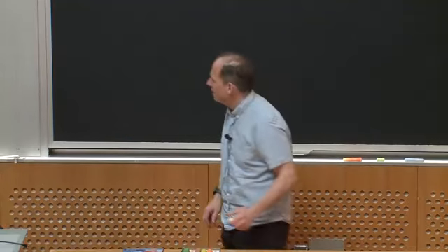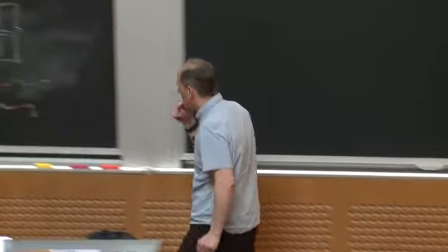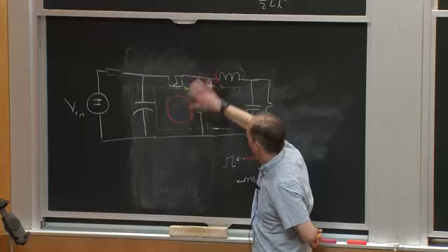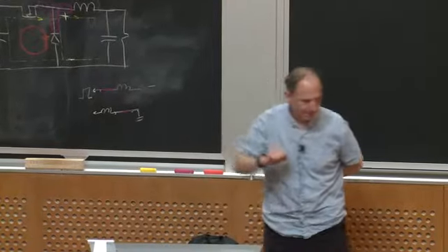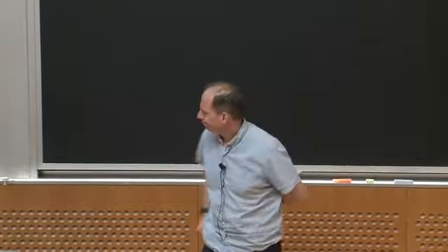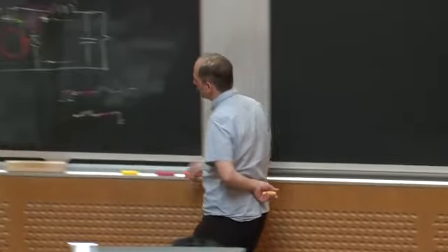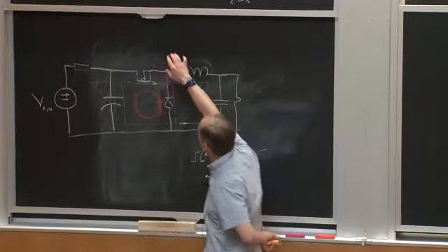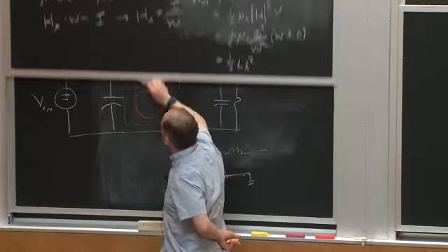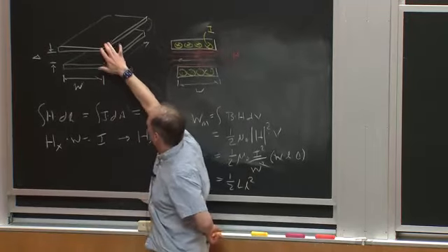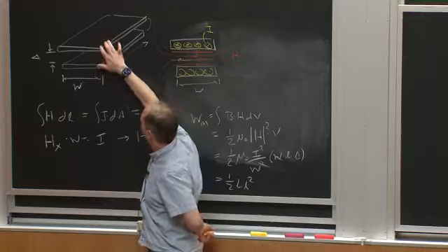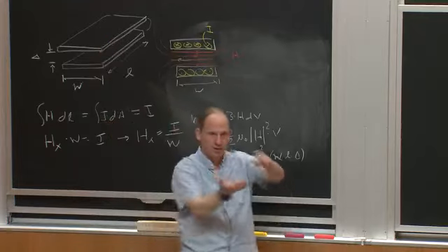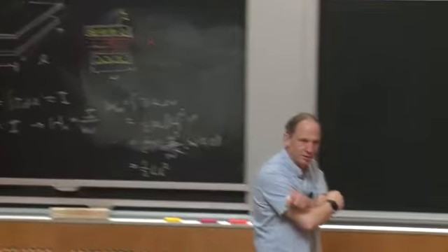Now, what would be the equivalent of that for this loop? What happens with the parasitic capacitance? Suppose I have some trace, this is my switching node and this is, say, ground or some other node, and I'm asking what's the capacitance between these two pieces of metal that are very close to each other.